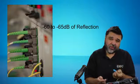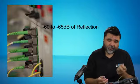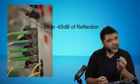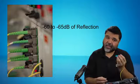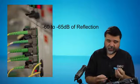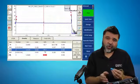So if you're dealing with amplified systems, the lower the reflection, the better off you are. And so we're starting to see a lot of APC connectors being deployed heavily, particularly in the GPON market. And so one reason why it's important to understand the connectors is anytime you look at an OTDR trace, you need to be able to interpret the data.